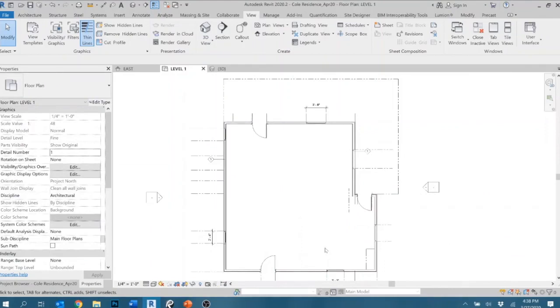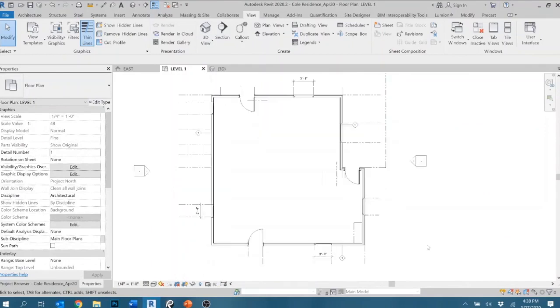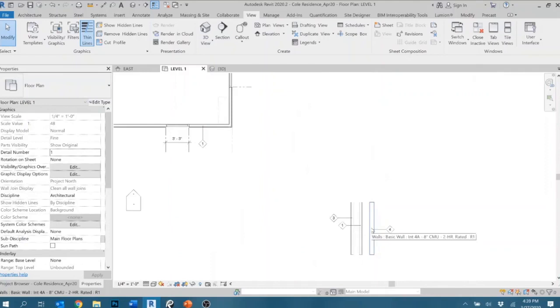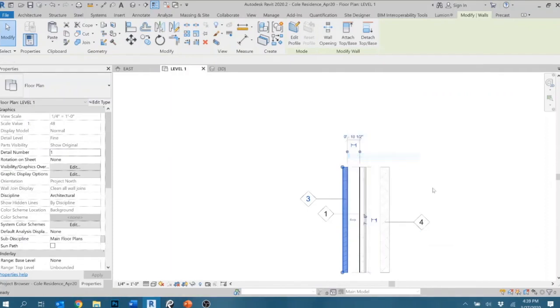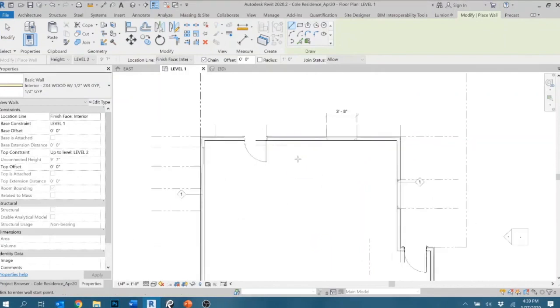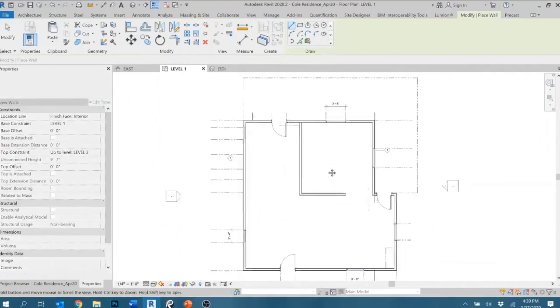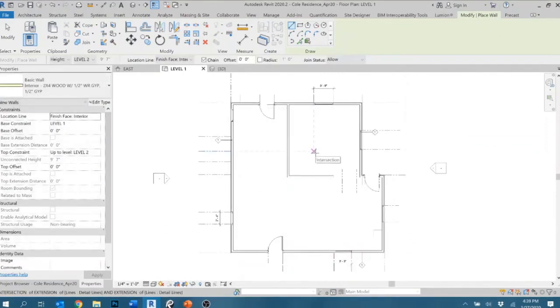Now I'm going to spend time locating the interior walls. Before we start offsetting in the interior for interior walls, let's use the same method of getting the project walls in and refining them later. I had the other interior wall type pre-made down here as wall type 3. I can right click that, create similar, and begin drafting the walls of the interior. Why don't you go ahead and do that, and we'll pick up with offsetting interior dimensions.